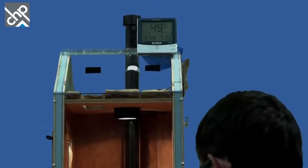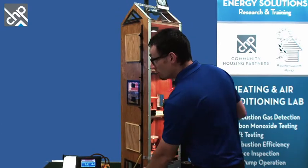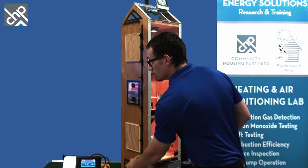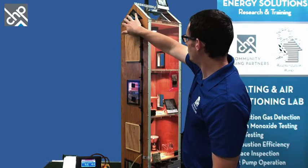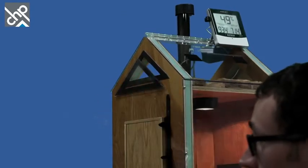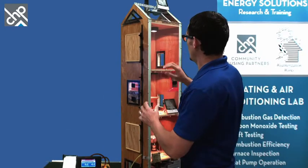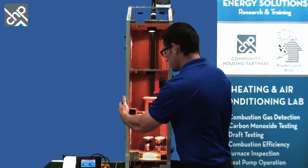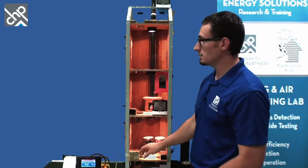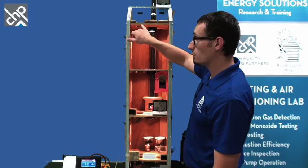And then I'm going to turn this to the side a little bit so you can see that each of these spaces have venting. So this crawl space door slides open and closed, so we've got venting here. And then we've also got attic venting high in the building, so we're going to have that connection to the outdoors. So we do have some sort of opening high and low. This is in the exterior portion of the building. And then on the inside of the building, I've got little slides that I can actually change the connectivity to those spaces. So I can open a hole down here inside of the crawl space. I can open a hole here between the house and the attic.